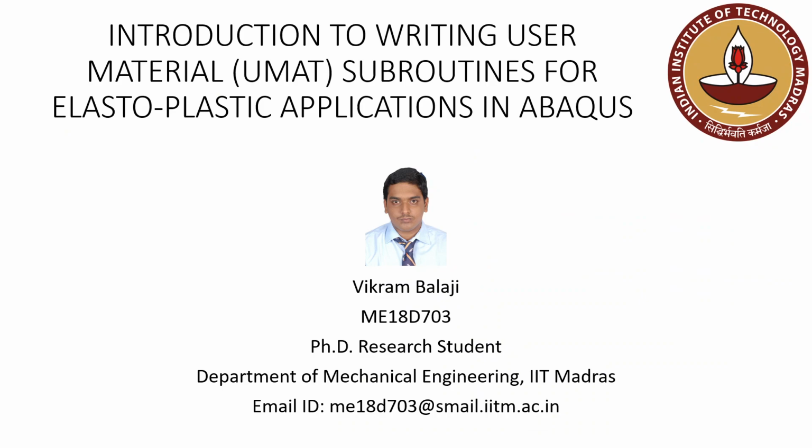So hello all, welcome to the second video in the series of Introduction to Writing User Material Subroutines for Elastoplastic Applications in ABAQUS. In the last video we saw the software prerequisites, that is, what software we need to install in order to implement user subroutines in ABAQUS. Apart from the ABAQUS software itself, we saw that there are two other pieces of software we needed to install: one is Visual Studio and another is the Intel compiler. We also saw in the last video how to link both of these to ABAQUS.